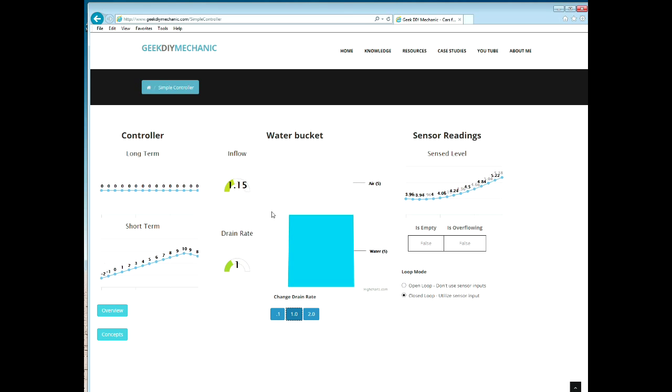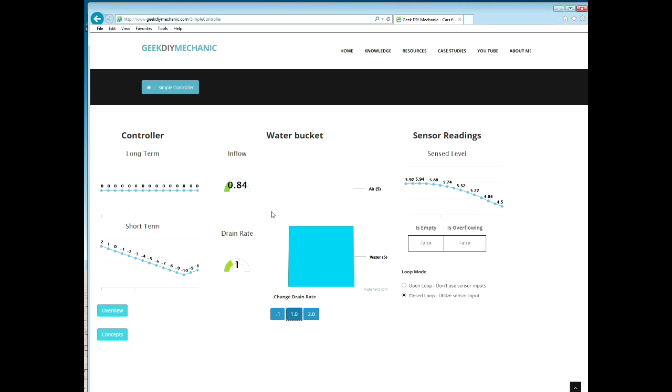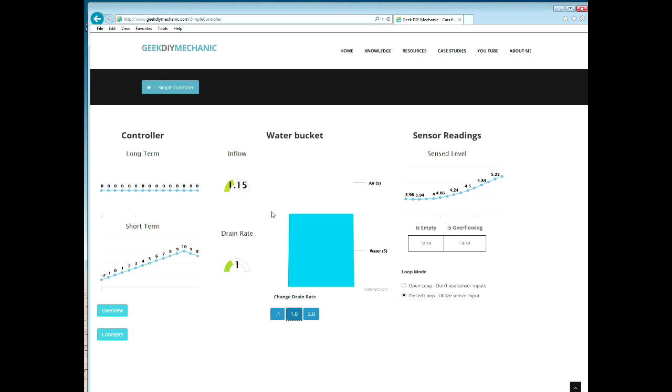So long-term and short-term values in a car or in this demo can be used to tell if the controller is making up for something. Remember, the engineers modeled the controller for specific behavior of the system given a stimulus. And when it doesn't match what they engineered it and mega tested it, you'll see those change. So when you look on your scan tool and you see long term either positive or negative, something is up.